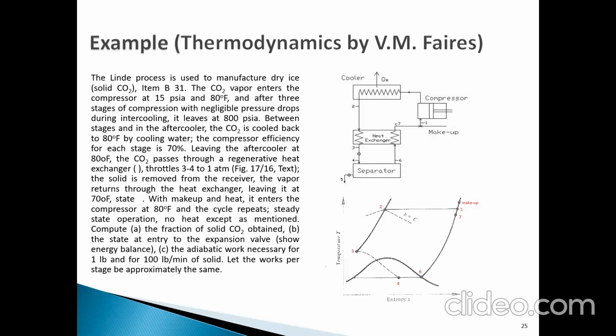Steady state operation. No heat except as mentioned. Compute A, the fraction of solid CO2 obtained. B, the state at entry to the expansion valve. Energy balance. C, the adiabatic work necessary for 1 pound and for 100 pounds per minute of solid. Let the works per stage be approximately the same.